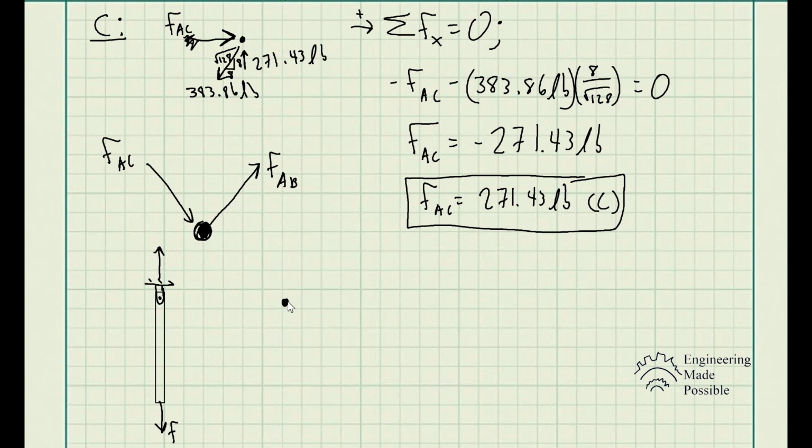And so whenever you just draw the member here, we have the member, the force within that member itself is being pulled down. So this is the action of the member being pulled downward at this joint, and of course the hinge itself has to react equal and opposite of that for force equilibrium.